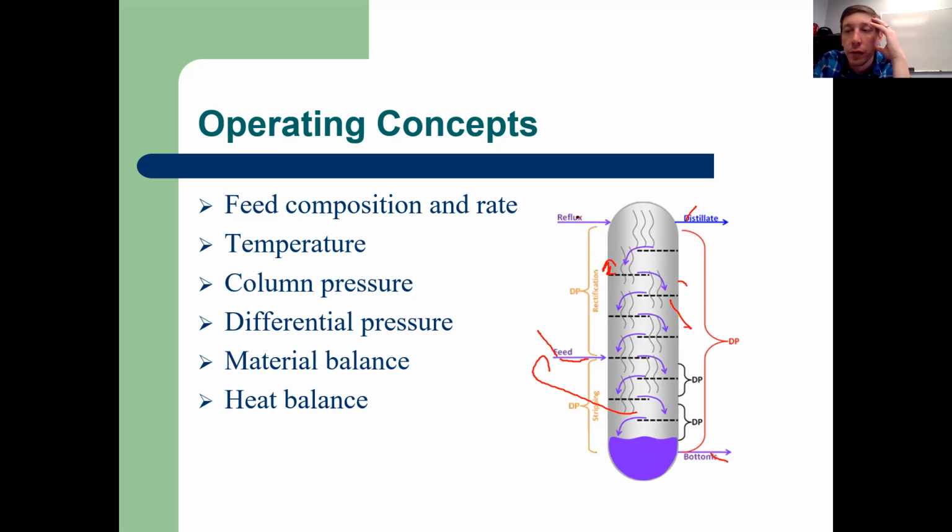And we need to up the reflux going in. We need to cut that back, because if we get too much bottoms product up here, then we have the chance of sending it out in the distillate, which is not good because it contaminates our distillate. And so we have to monitor that.